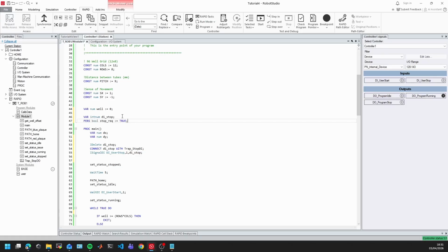So what am I doing in here? Basically, I am creating this variable as a persistent variable. And what is a persistent variable? Even if we have some troubles, or if this is shut down, these variables do not get erased from memory. So they are retained in memory. For example, if there is some sort of shutdown or power off, or whatever happens to the machine, these variables are retained in memory. So they are really good for certain processes. We have to be careful not to use many of them, but they are really good for this type of purpose.